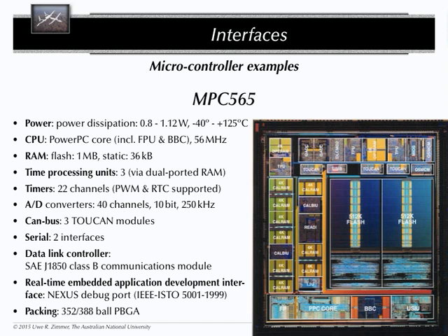This extra debugging device can do a number of things. It can actually look into your running, bleeding heart CPU. It can tell you the register values while this thing is running live with your SPI interface, with your Nexus debugging port, which pumps out this information as you requested while the CPU is actually running.